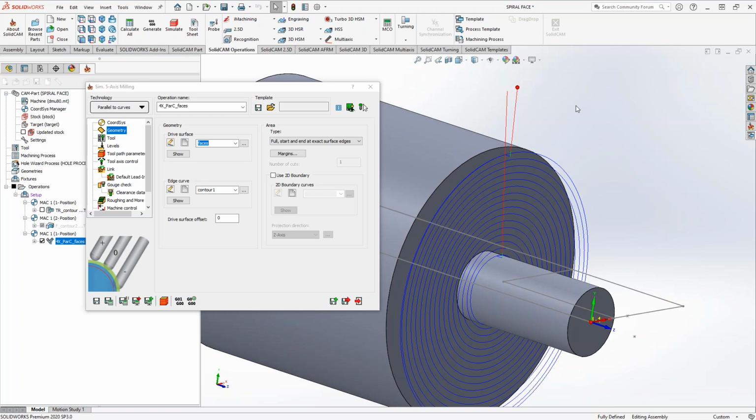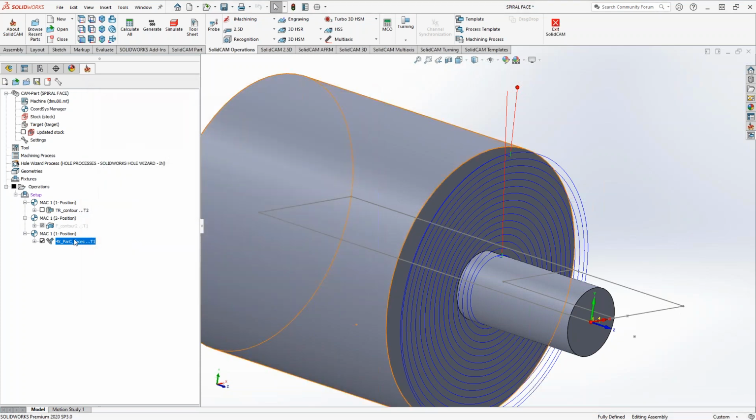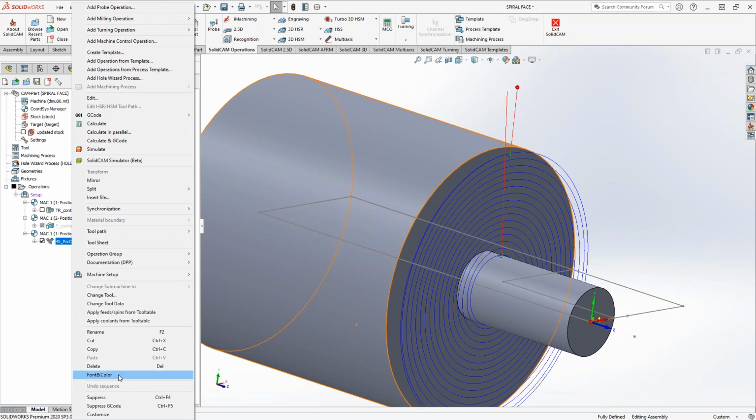Sorry, go ahead. This is done in 3-axis, and if you were using a ball mill and we didn't want it to come back and recut all of this, what Mark could do is switch it over to 5-axis toolpath, tilt that tool over by 20 degrees, and it'd do the exact same motion that way. So we're not constantly rubbing on the side. It gets to a point where we start shanking out a little bit, where we could tilt that tool over at 20 degrees for you as well. Might as well just show that since we have some time.